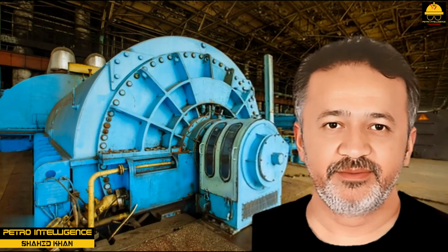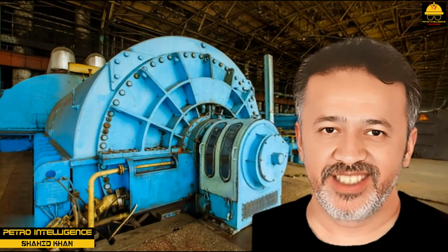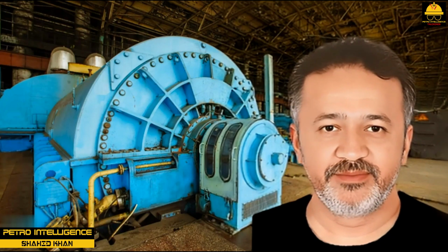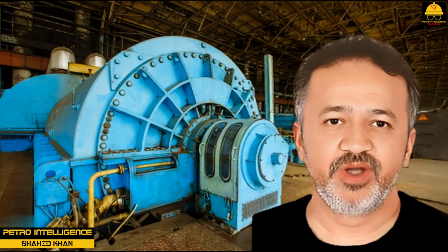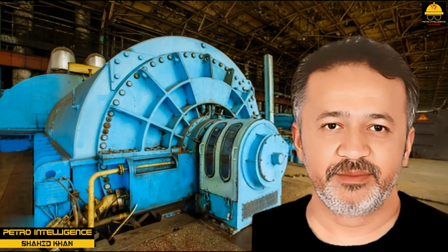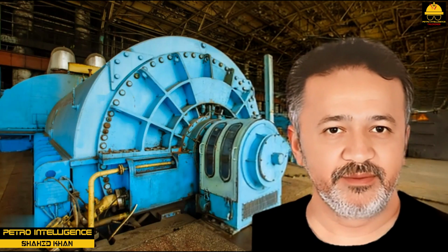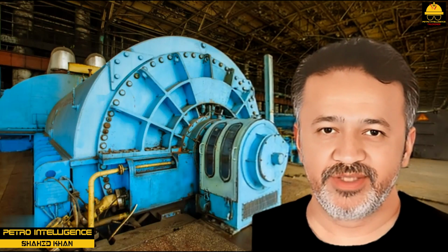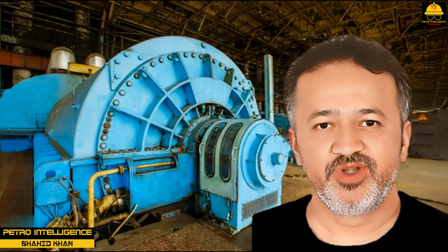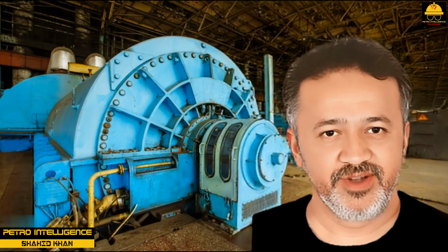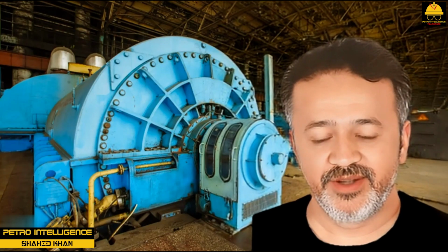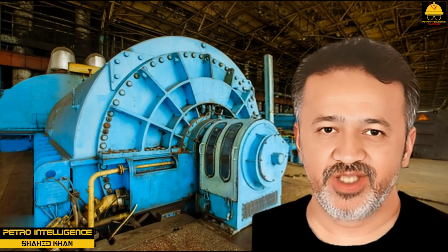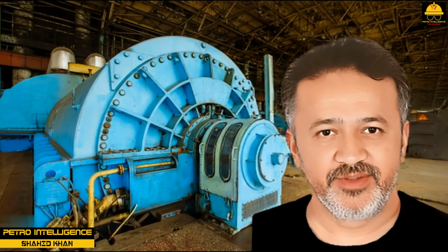Other parts. Steam turbines have a hand speed changer capable of making 10% speed range adjustments. A sentinel valve, a spring-loaded automatic relief valve, makes a high-pitched noise when turbine speed approaches the design maximum. An overspeed trip is a safety device used to shut down the turbine when it exceeds 115% of rotational design limits. A weighted spring attached to the governor hub is used to close the governor and stop valves.